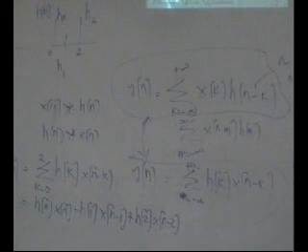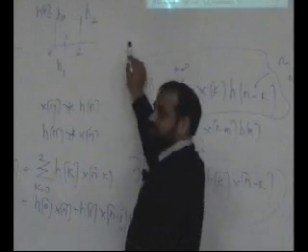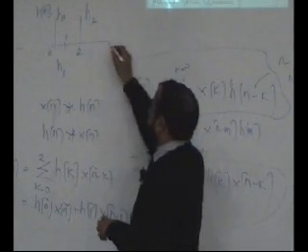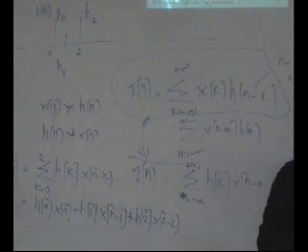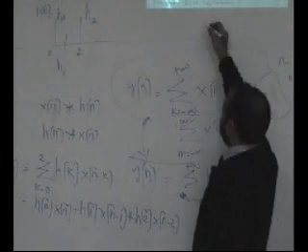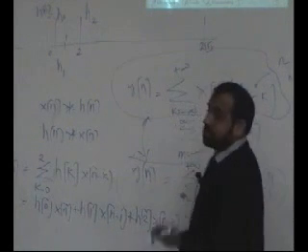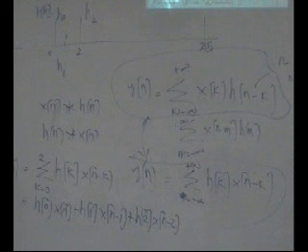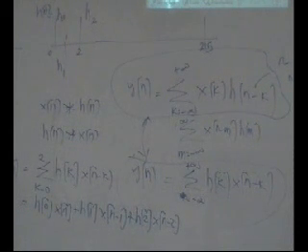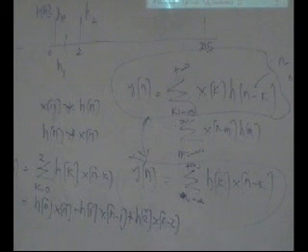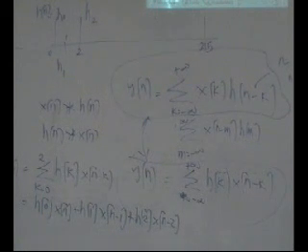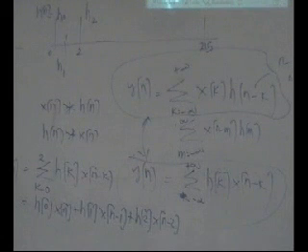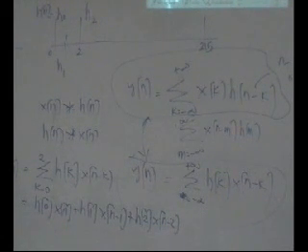If I say no, I really cannot design a system with 3 constant values. I really need to design something. You ask me to design something and I sit on MATLAB and come back and say, oh, this is really taking 216 samples. What is meant by 216? If an impulse response length is 216, what is meant by that? To compute an output sample, how many multiplications do you need to do? 216. And how many additions? 214.